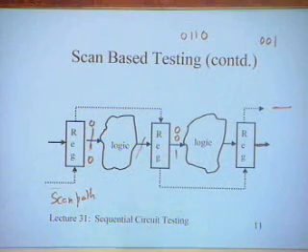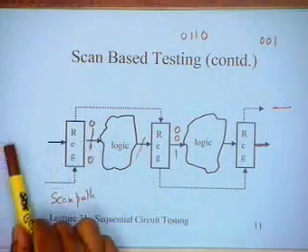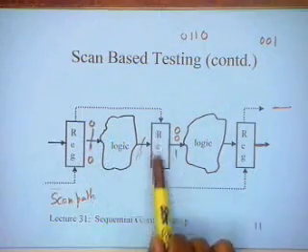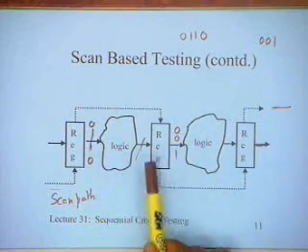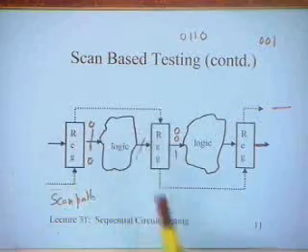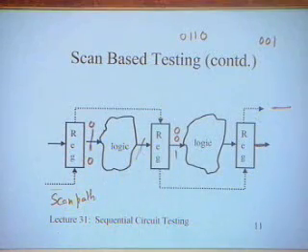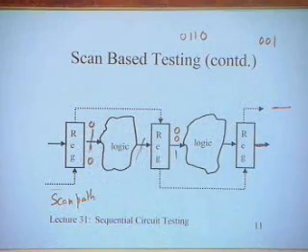Why am I doing this? The reason is that it is not possible to control through the normal logic. If I want to set this register to some pattern, getting that pattern through the functioning of the circuit may be very difficult. It's like generating a homing sequence for a vector through a very complex set of logic. It's not just a pure state machine. There are a lot of data paths.